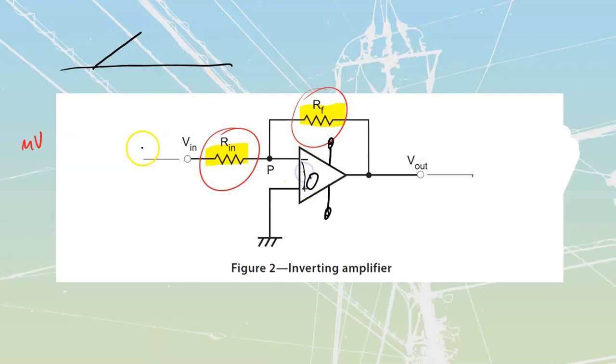As I take that signal and I start to climb, inside of here, we're going to see here's that signal that we are feeding in. It's coming in onto this input over here. As that voltage goes up, I'm going to drop some of that voltage over top of my input resistor, but the rest of that voltage is then going to appear across this little input over here from my inverting to my non-inverting, where it's going to get read, and as it gets read, it is then going to cause a change to happen.